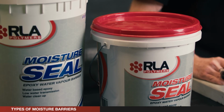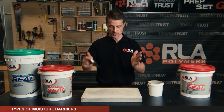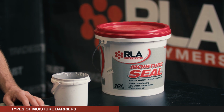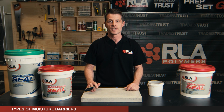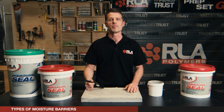RLA's moisture barrier is a two-part water-based epoxy coating designed to provide moisture and vapor barrier properties. Applied to concrete surfaces in a couple of coats, it prevents rising damp and residual moisture that might be in the substrate to protect the overlaid flooring finishes. It comes in two parts, equally mixed, and basically just spread on by brush or roller onto the substrate. Here's some we mixed up earlier, so we'll show you how it's applied.